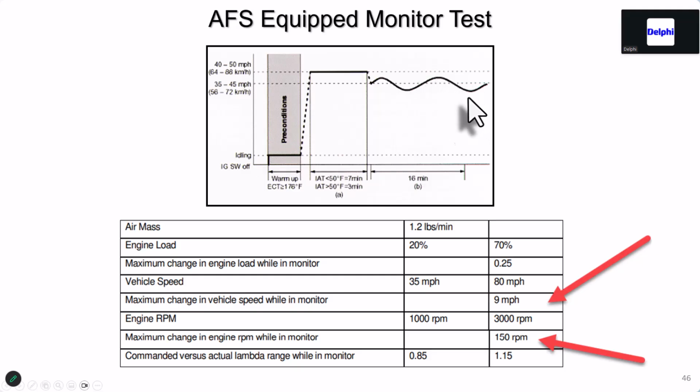We want to be steady with the throttle, up and down, usually about 9-10 miles an hour, no more than a couple hundred RPM change, just rhythmically. If you're doing this on some of the smaller high-revving four-cylinder engines like Toyota, my recommendation is if you're up at 50 miles an hour, when you do this decel, hit the overdrive button. That will pull it down faster.